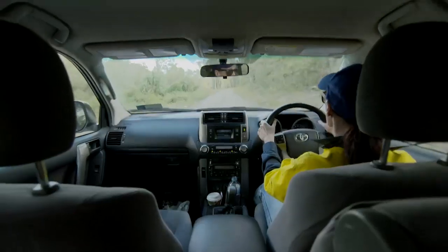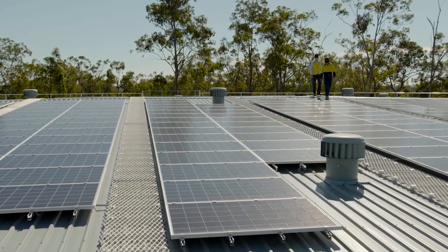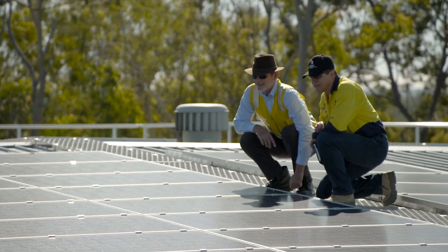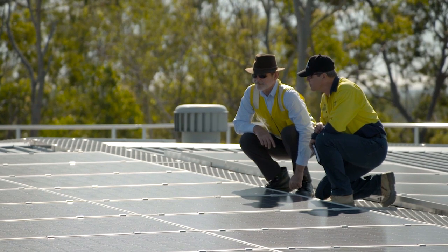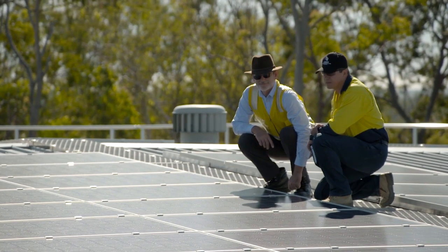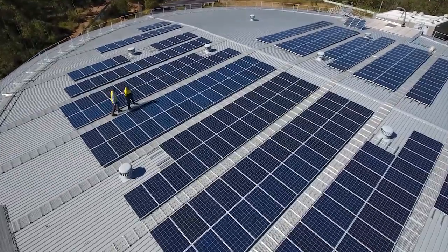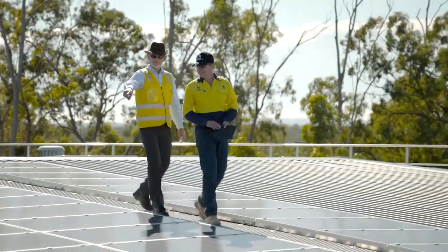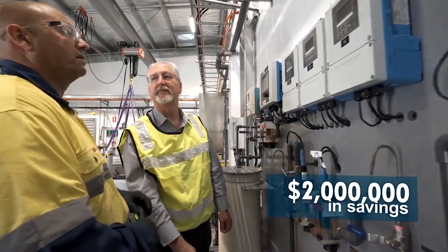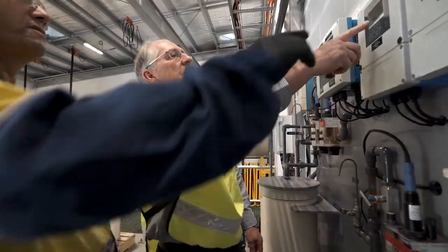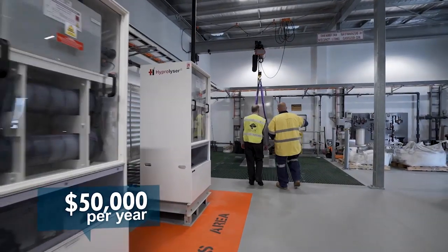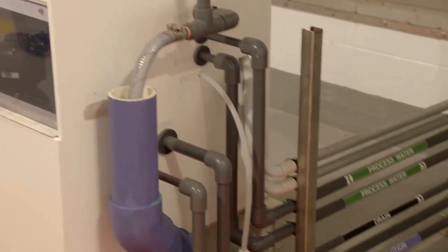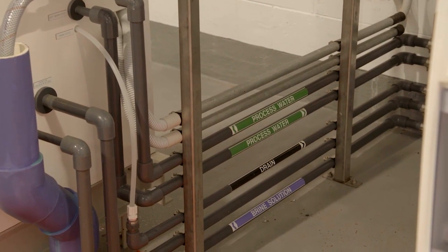Council's Logan Water Infrastructure Alliance stepped up to find a solution for water chlorination in this challenging location. The Alliance assessed a range of chlorination options, but one stood out as being the most sustainable long-term. This option was reliable, safe, and didn't rely on mains power or a sealed road for chemical deliveries. It also saved almost $2 million in capital costs straight away and about $50,000 a year in operating costs. Electrochlorinators would produce enough chlorine to treat almost 13 megalitres of water every day.